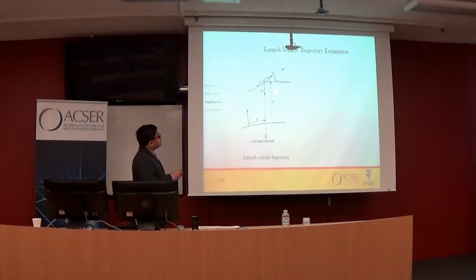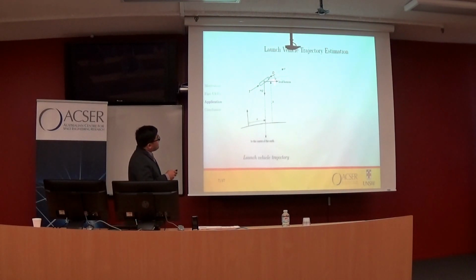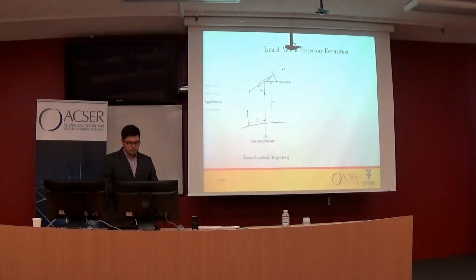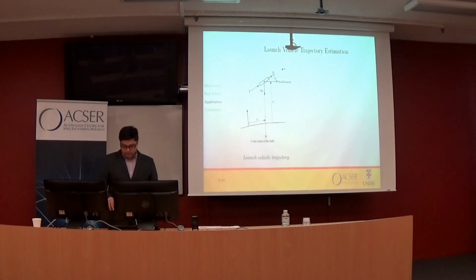So to express this time evolution of x and h, we need to also know the velocity, the atmospheric drag, the thrust, and also the flight path angle, which is the angle between the local horizon and the direction of motion of the launch vehicle. So how nonlinear it is, to give you a bit of a sense.